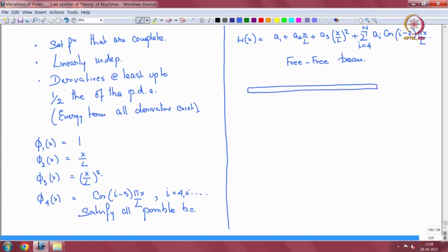If you want to implement restraints, rotational restraints, then use a rotational spring with a penalty. If you want to restrain vertical displacements, use a vertical spring with penalty. And they show very good convergence and very good numerical behavior for a large number of terms. The tables are presented in the text, not showing them here.